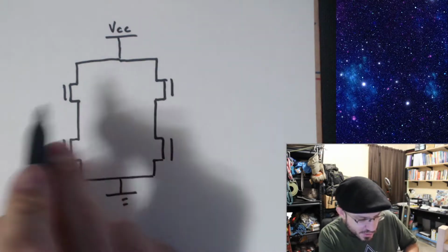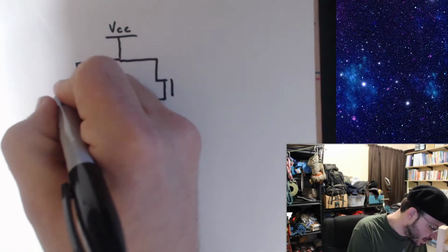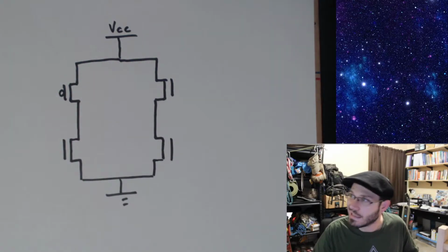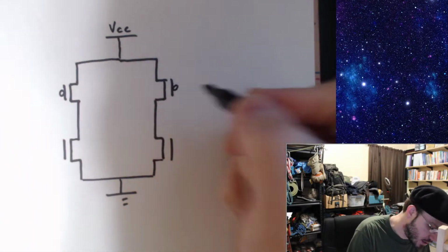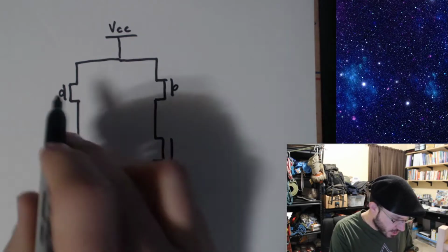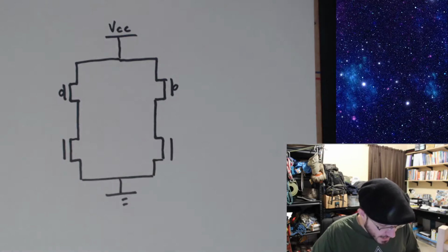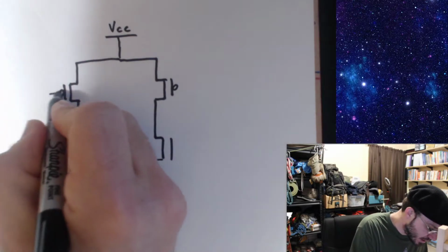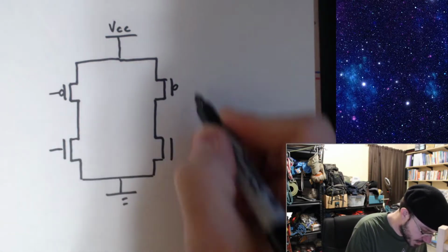For the high side switching, I'm going to have to use a P channel for that reason that I discussed earlier in class. Both of these will have to be P channels for the high side. For the low side switching, I can just keep that as regular N channel MOSFETs.